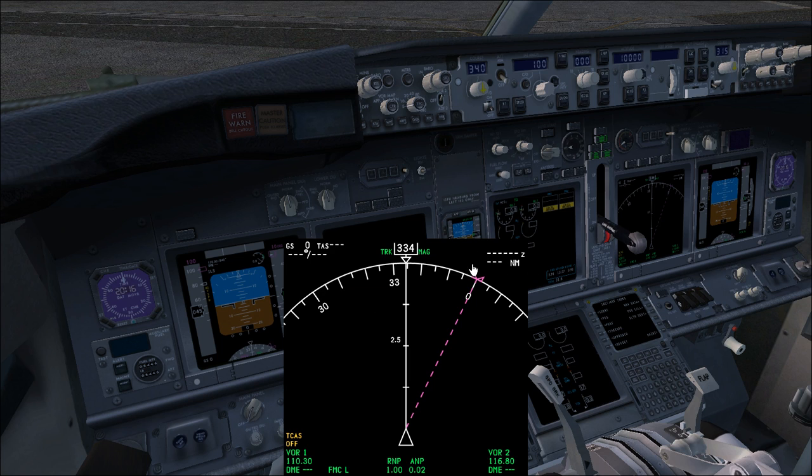Here we have the waypoint indication. Up here we have the waypoint indication. Usually when you have a route loaded up into the FMS, the route is displayed into the map display. Actually there is the next waypoint in magenta here, the estimated time of arrival over the waypoint here in Zulu time, that actually is taken by the clock, and the nautical miles to the actual waypoint displayed here.